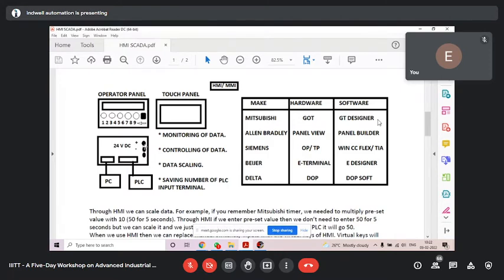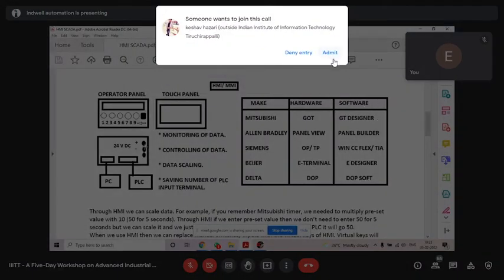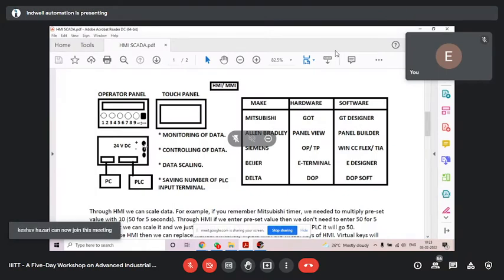One port we use to communicate our HMI with the PLC. So you can say it is an interfacing port. We interface HMI to PLC through the interfacing port. I shall tell you many things about HMI today. Don't be worried. Keep patience. Another port will be used to send or receive the HMI design, or program, let us call it. The HMI program is like a visualization design, so that design you have to send or receive through one port.